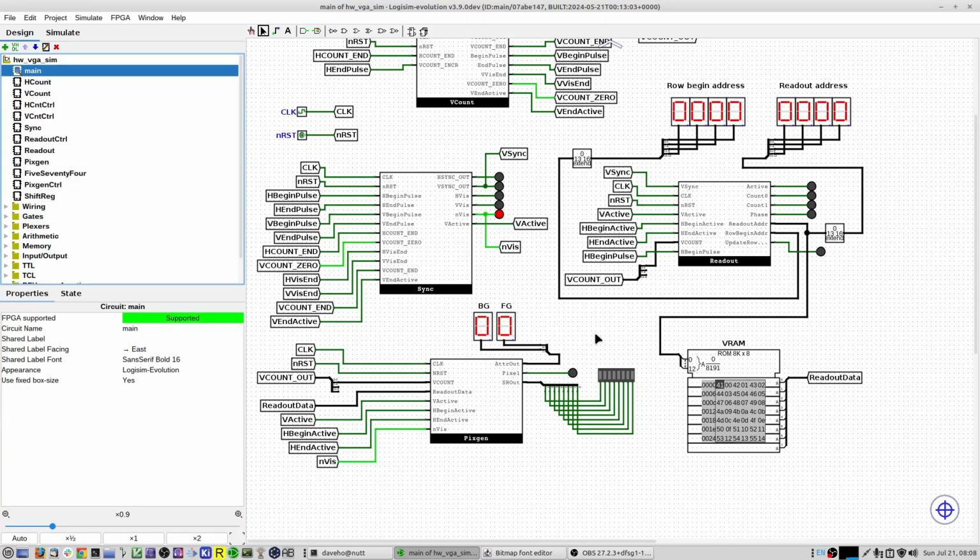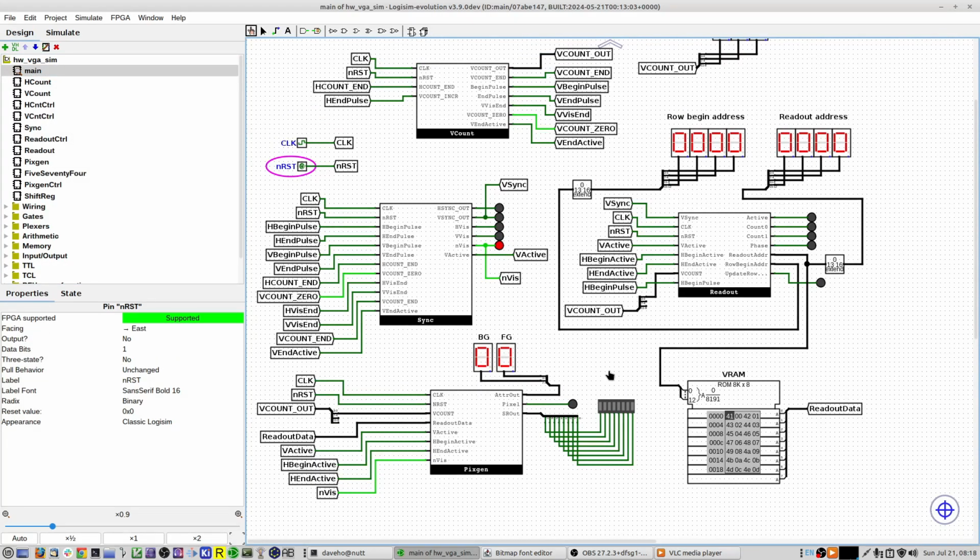And that's a little bit tricky, but what I did is I'm just visualizing the attribute register, so the background and foreground colors, and also visualizing the contents of the output shift register. And when the simulation runs, I should see those values changing as data is sent to the output module. So the interesting question in terms of using the simulation is how do we know that the values that we're seeing in the attribute register and the shift register do actually indicate correct behavior?